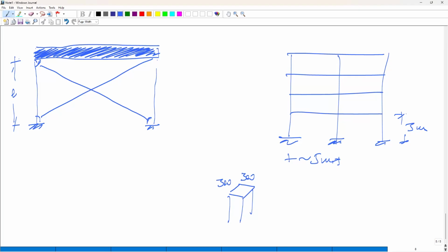And we have said it's a wise practice to keep the width of the beam the same width of the column, so that your formworks are easier. But most of all, your reinforcement, if you have to anchor and to guarantee the continuity, you do not have to make your reinforcement make strange bendings, because if you have a beam that has to restrict, your reinforcement has to do something like this.